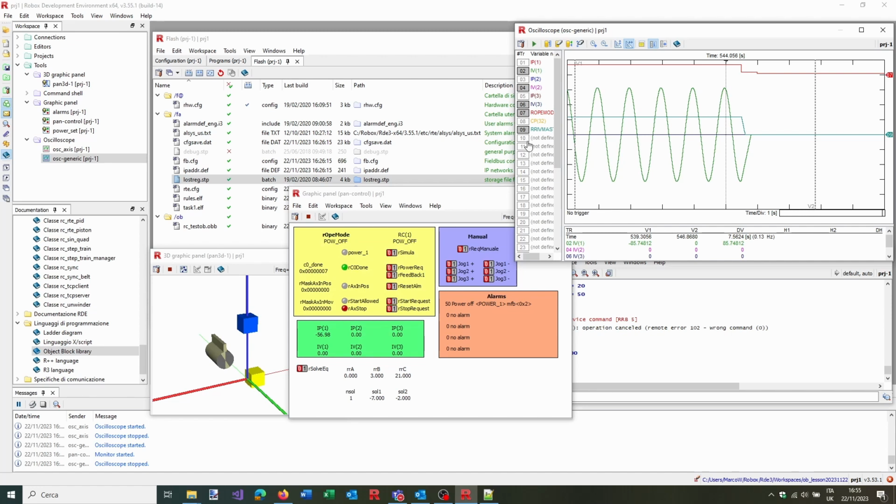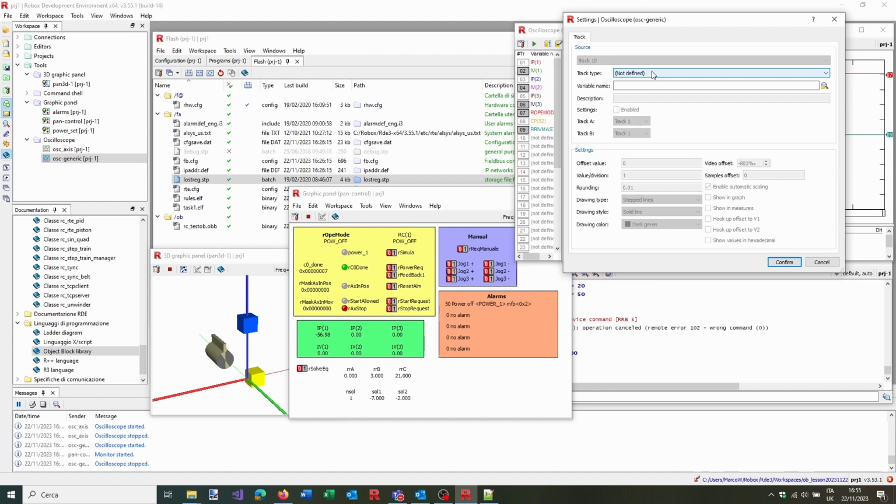We can do some more debugging and see some more of the power of the oscilloscope. Here, if you want, you can do some calculations, like multiplication or derivatives and integrals. Since we wanted to show that this is a ramp and not a piece of the sinusoidal, we wanted to see the derivative, so the acceleration.